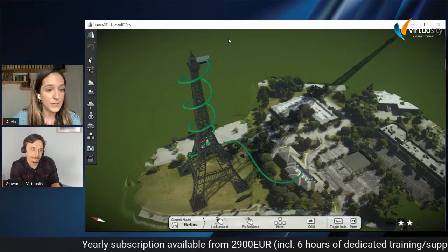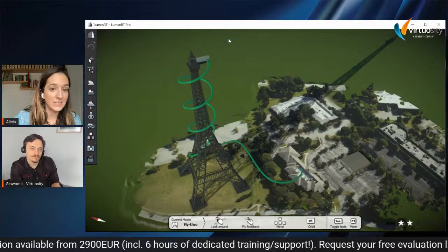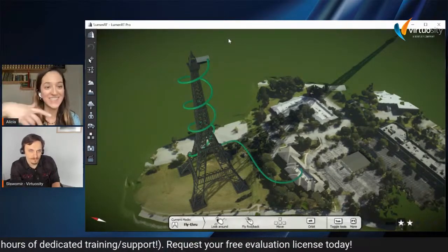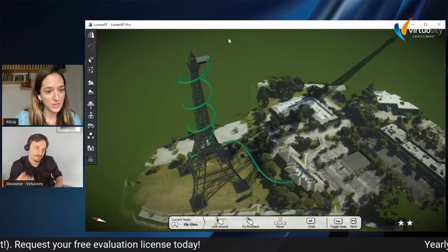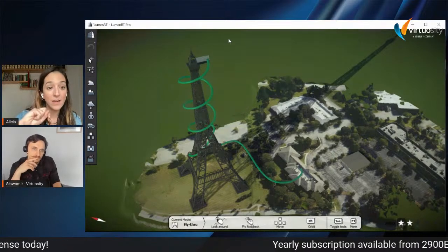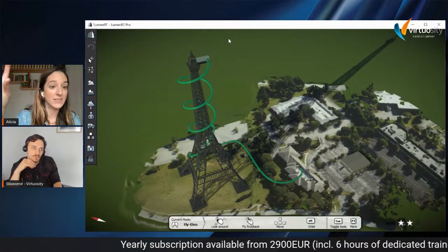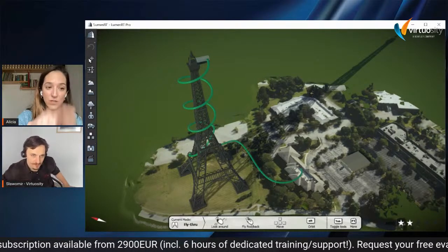Basically you've uploaded your 3D mesh, you've added any elements that you need for that project, like buildings, Eiffel Towers, even creating a slide or different elements within ContextCapture Editor, and you can assign materials and so forth. Then you go into the visualization tab, and you have a button that says LumenRT. You click on that, and then you go into the LumenRT application, which is the one that you are seeing on the screen.